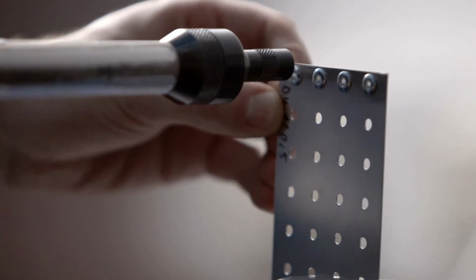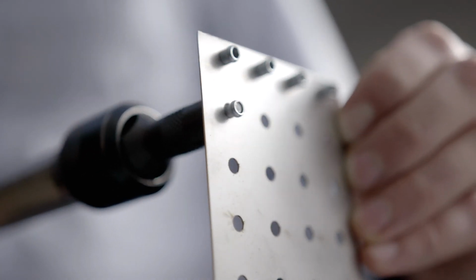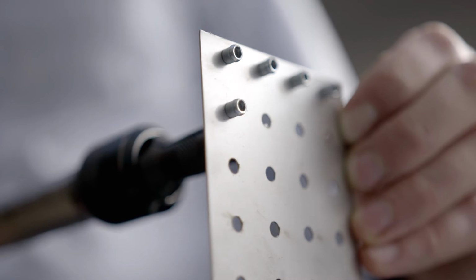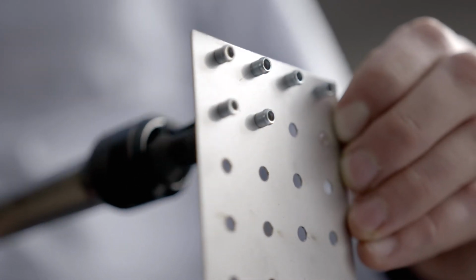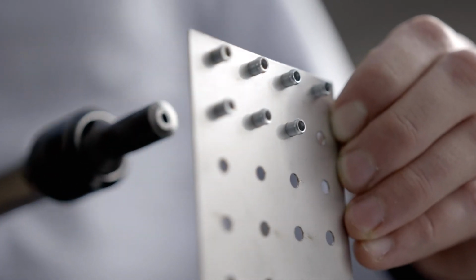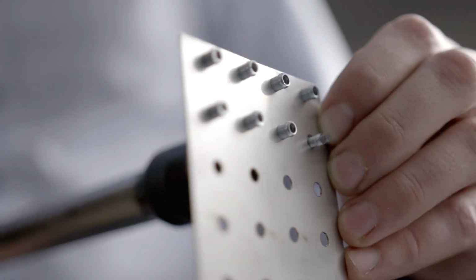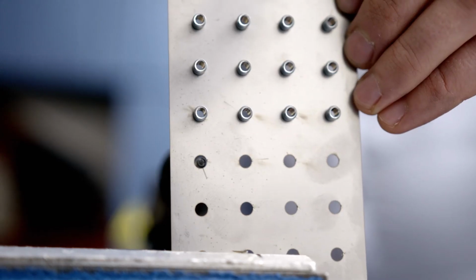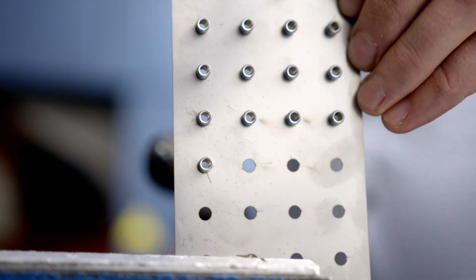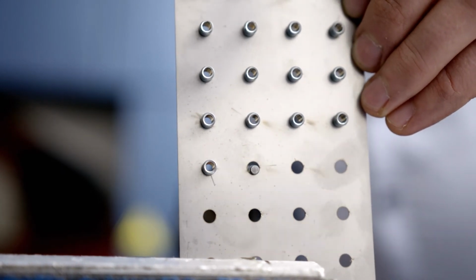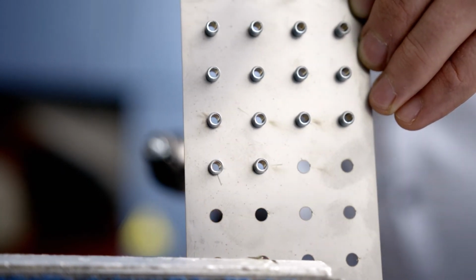Depending on the speed rivet type and size, up to 90 rivets can be mounted on one mandrel. That results, with one reload process of the tool, in an installation speed of up to 60 rivets per minute in a semi-automatic process. As the mandrel gets pulled through the rivet, there is no remaining mandrel within the installed speed rivet.